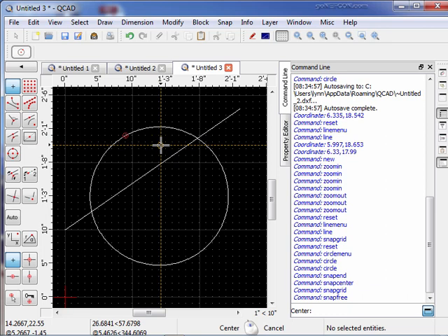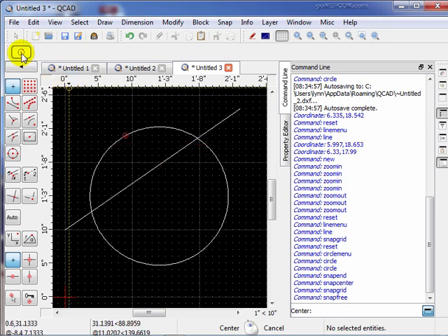I've already selected a tool, which was the circle with the center point and a radius. And the command line already knows that because it's waiting for the center point coordinates. So to activate the command line, I have to hit the space bar. That places focus in this little text box here of the command line. What focus means is that anything I type on the keyboard will go into this text box. We assume focus all the time in many situations in Windows programs, but here we have to be more concerned about it. Once I get the flashing I-beam, I know I'm in focus, I can type.